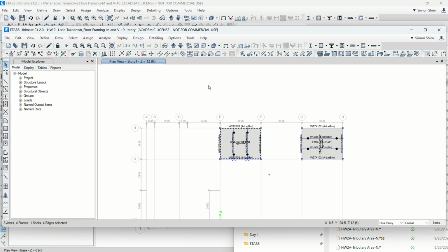Let's say 24 feet length. Dead load is self-weight. Live load is either 100 psf, let's say. The self-weight we need to calculate for the 3-inch metal deck depth plus the 3.25-inch concrete topping. So we take 3 divided by 2, plus 3.25, so this is 1.5 plus 3.25, about 4.75 inches.